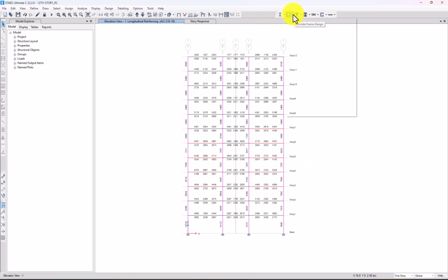So if we go back to the verified one, from 151.85 is passed. So in the next, we can even ignore this one, it's okay. We can consider this is okay, because there are two ways to solve it. One is to increase at least this area to 600 by 800, or the upper to 400 by 700. So bring some changes. Now the beam design is completed, and we go to design the slab.